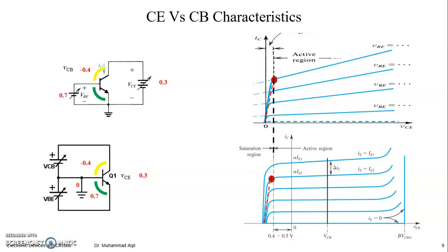What was the statement? Let me state it once more. It is that when we took emitter as common, we drew every voltage with reference to emitter, right? Base to emitter: the input characteristics curve IC versus VBE, so B with reference to E. Output characteristics curve shown here, IC versus VCE, right?